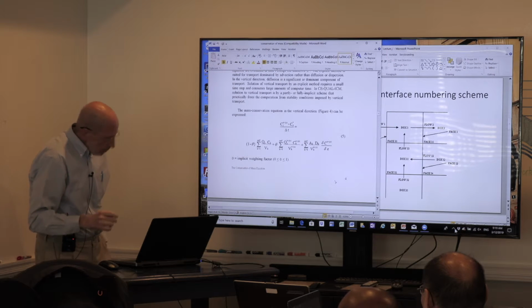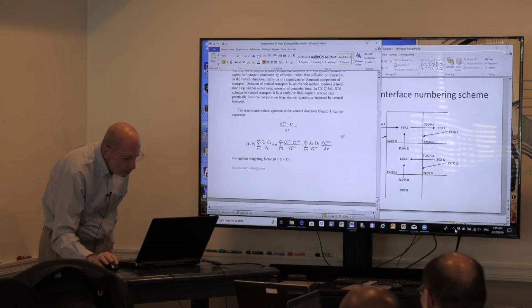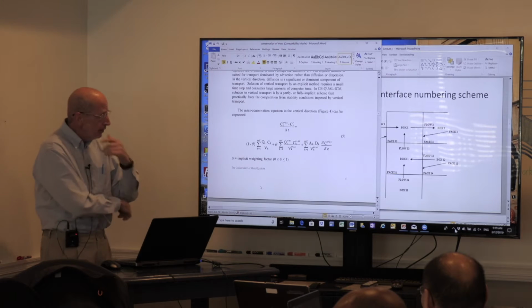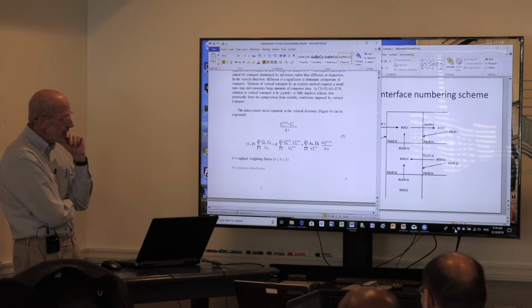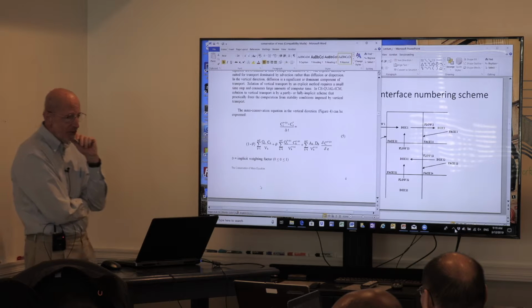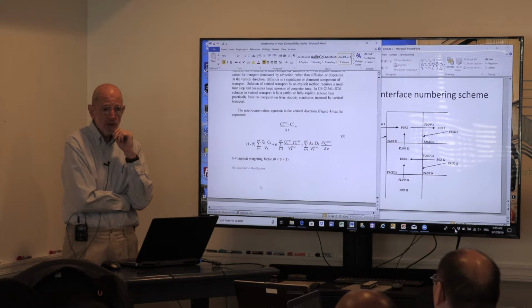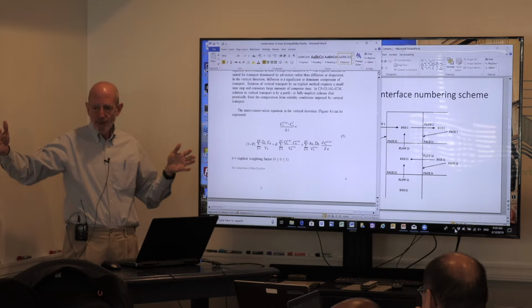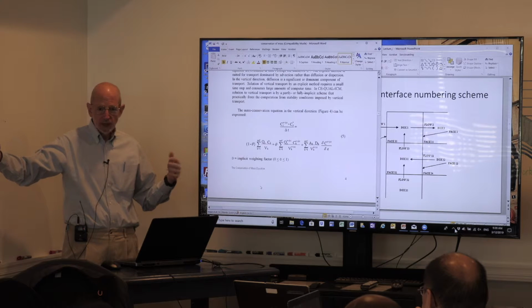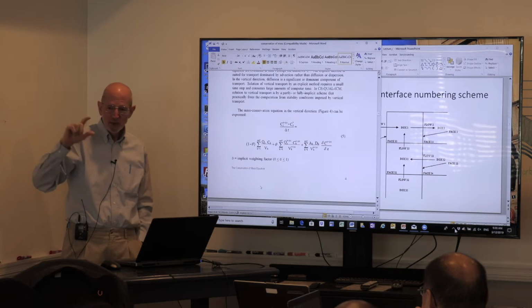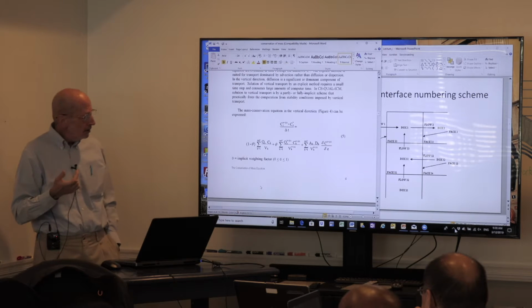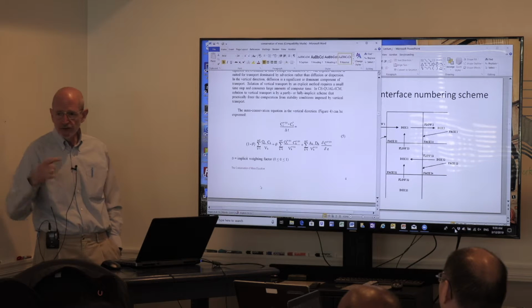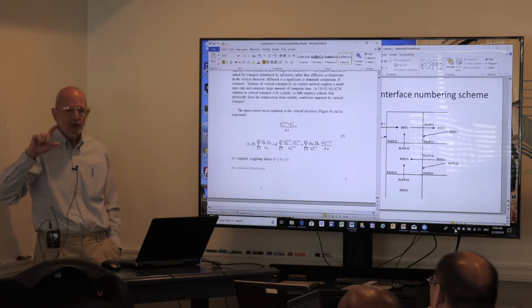Okay. And what you see over here is that this is the diffusive transport term, and we run that one fully implicit. We don't give you an option, and the reason is, like it or not, you need the stability, okay? If you think about these cells, they're order of magnitude a kilometer in length and breadth, and they're order of magnitude a meter in thickness. So the stability requirements can be very different for the longitudinal and lateral versus the vertical.